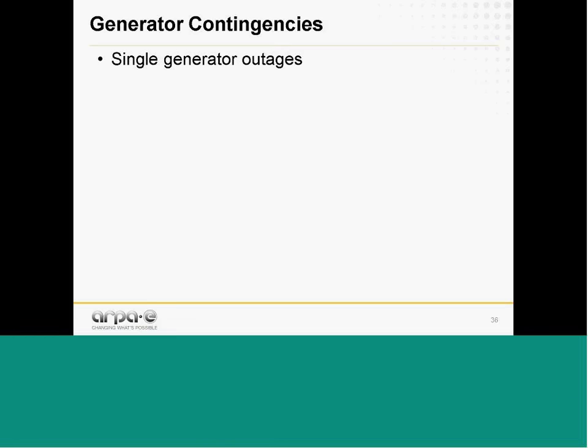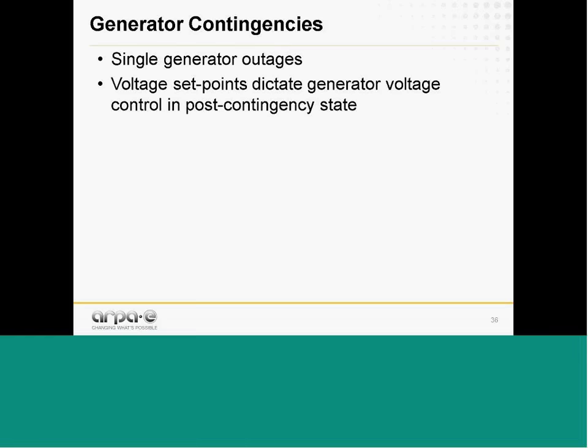All right, some more on generator contingencies. I talked about the real power response. Next, I'm going to talk about the reactive power response. This is, again, following the traditional mechanisms that we use in the industry relative to pre- and post-contingency behavior and corrective actions. This is a voltage set point rule, with preventive and corrective actions. I have instructed you to maintain your voltage at that bus at 1.06 per unit. You are going to follow through with that 1.06 per unit requirement as long as you can.